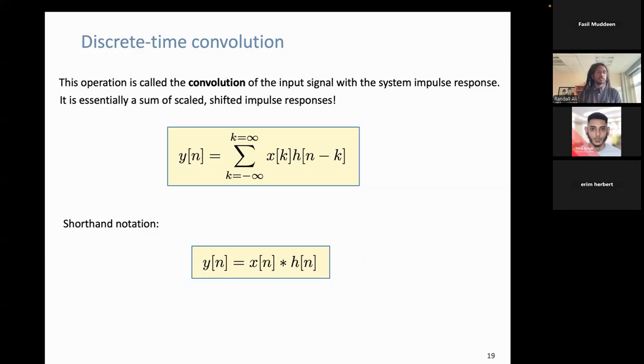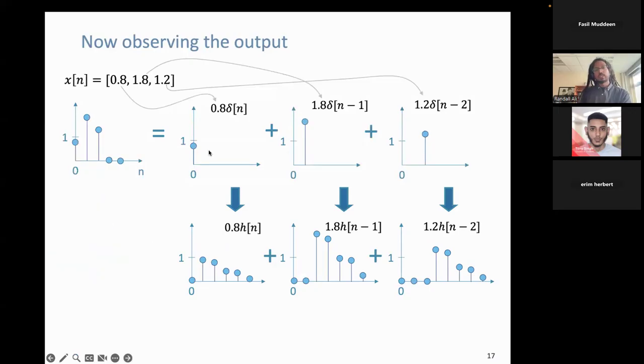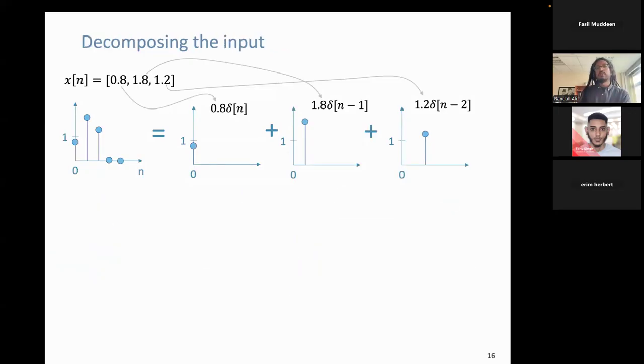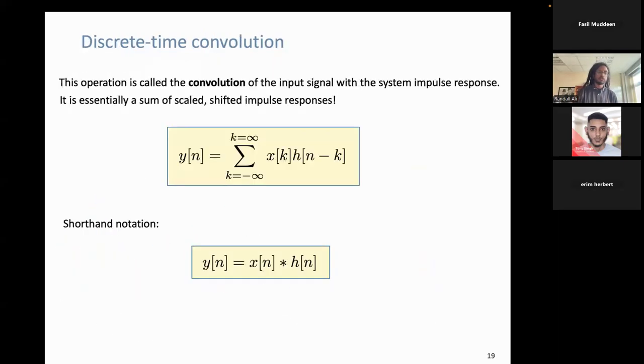Once we have this impulse response, we could essentially synthesize the output of the system for any input, and I do that through a discrete time convolution. And that was because we were able to view our signals, in general, as being decomposed as a sum of scaled and shifted impulses. That's another way to look at how you get to a discrete time convolution in this case.